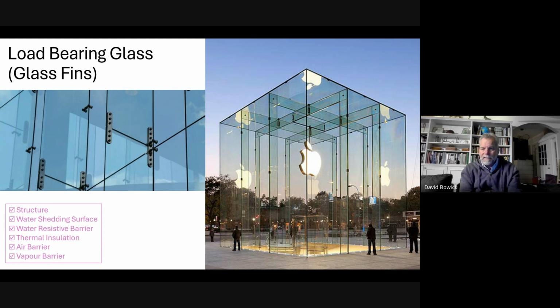The challenge of glass, interestingly, in a load-bearing application, I always presumed that buckling is what controls. But it seems that in load-bearing glass, once you satisfy your deflection criteria for wind, which I didn't share actually when we were talking about glass, you can have up to something like 1% deflection of glass under wind load. So it's quite a bit.